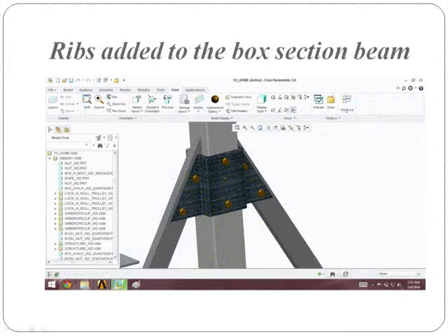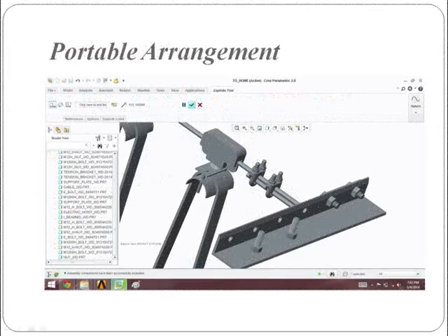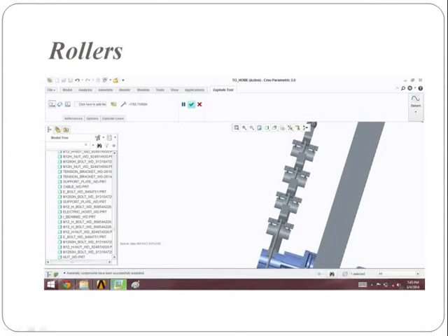Beams are structural elements where the length is several times larger than the dimensions in any of the two other directions. All beam theories describe the beam as a one-dimensional structure, and the beam axis, denoted X, is in the length direction. The cross-sectional geometry is represented by a number of scalar quantities such as area and moments of inertia. The displacements and rotations describe the deformation of the beam axis, and the displacements in the cross-section are directly related to the deformation of the beam axis. The internal forces: axial force, shear forces Vz, Vy, and bending/torsion moments.